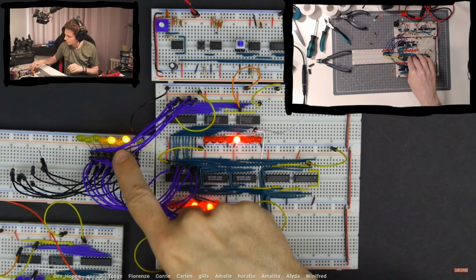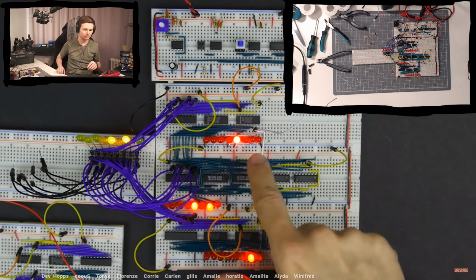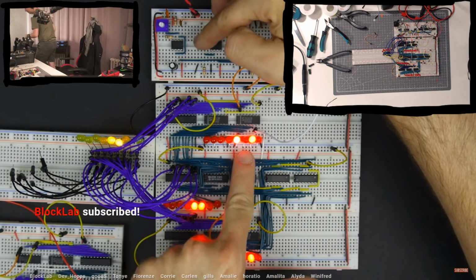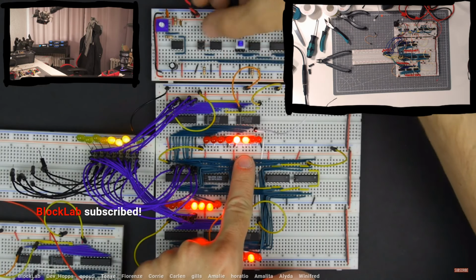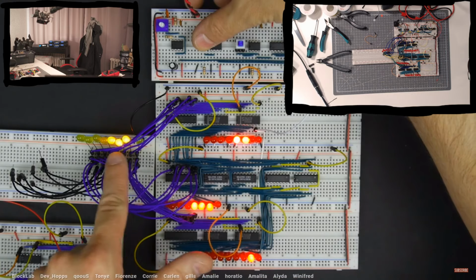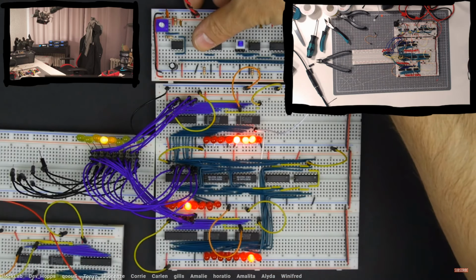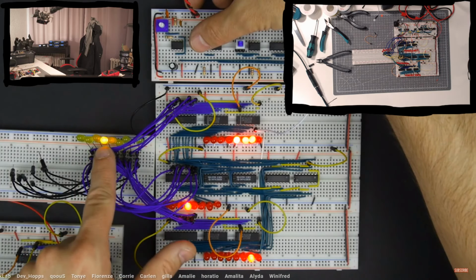And I think that's the key, is that it's almost instantaneous. So it's able to read in that 8. And then the next clock, it's going to read in the 10. And now there's a 12 on the bus. And next clock, it reads in the 12. The next clock, and now we have a 14 on the bus. The next clock, it'll read in that 14. And now we have a 16 on the bus. And so you can see each time the clock goes, it's adding 2.